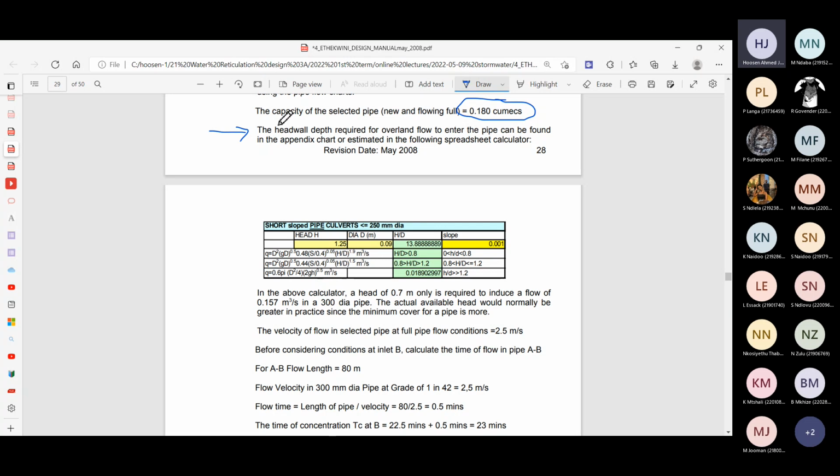Now, what happens in a culvert? Why do you need to do these checks for culvert design? When you have a culvert, the flow is controlled. You have what we refer to as inlet control or outlet control conditions. So let me briefly explain it to you.